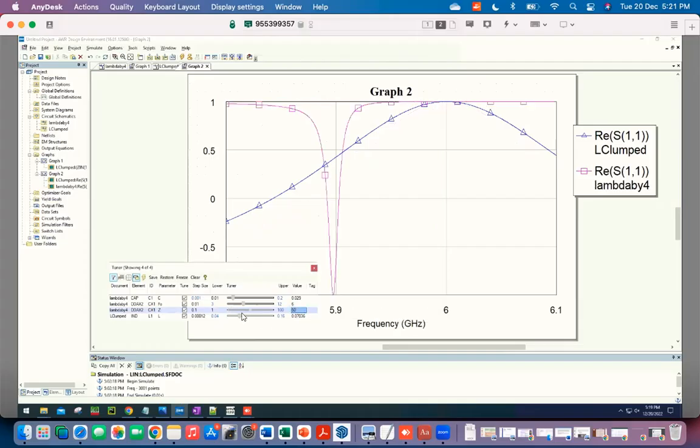Okay, so when we are introducing that capacitance, the effective capacitance will be some combination of the external capacitance and the internal capacitance. But L will be similar. Exactly. So because now the total resonant frequency is a combination of L, C plus C external, that balance is no longer maintained, because the balance is maintained between only the L and the C. So because there's an extra capacitance, depending on how much extra this capacitance is in relationship with the original capacitance, it will affect the frequency as well.